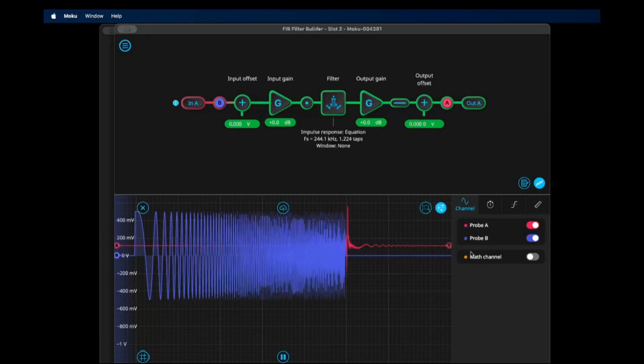And let's auto scale. Now we see a spike on trace A. This is a result of the pulse compression. The waveform, after going through the filter, is shortened in the time domain and thus has a higher peak power and signal-to-noise ratio. Now this is useful to determine the time of arrival. If you have multiple pulses overlapping in time, then this filter can separate them out temporally. And it's also useful for recovering a known pulse shape from a noisy background.